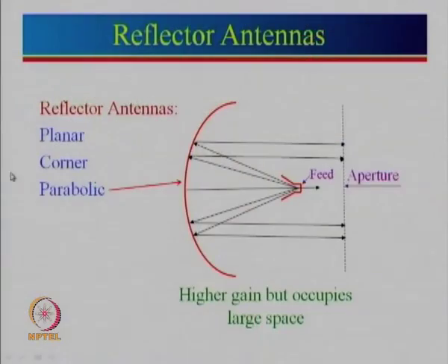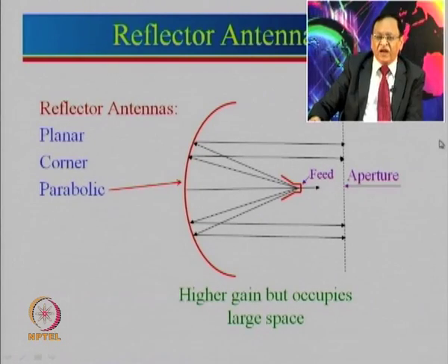However, parabolic dish antennas are used to design very high gain antennas. First of all, let us look at a very simple thing. You might have studied the parabola equation even in high school or initial engineering courses. What is the definition of a parabola? Rays coming parallel from far away, after reflection, concentrate at the focal point. It is the same principle used in the parabolic dish antenna.